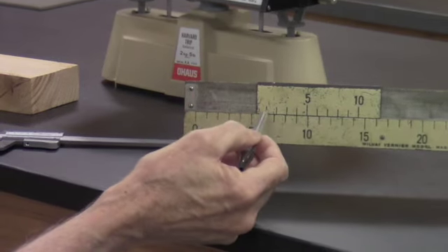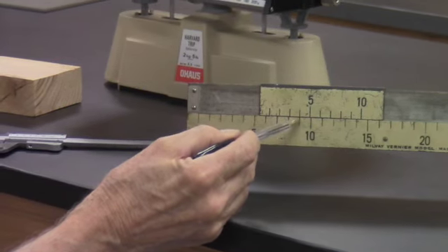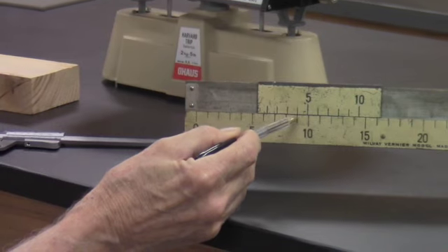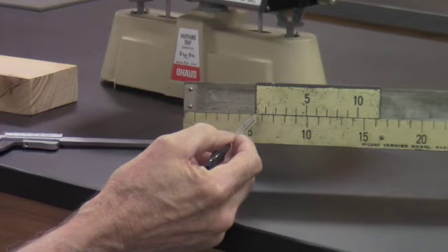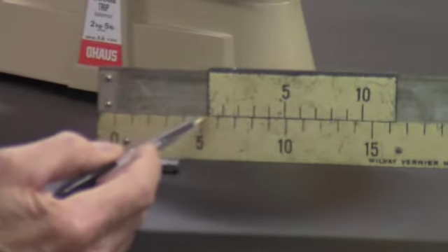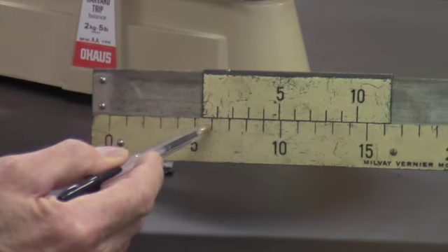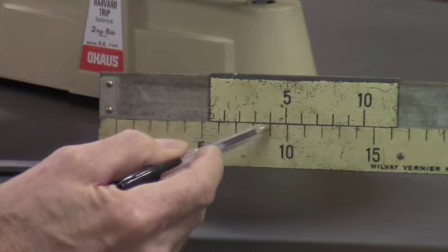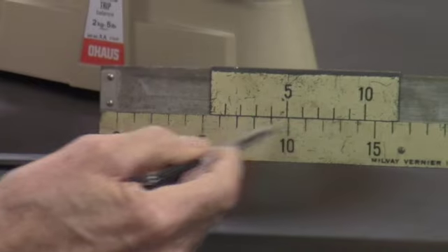And so if you look over here, this line and this line are lined up best above and below each other. And so what that means is this is 5 point, not 5. You probably look at this a little more carefully and see it's a little bit below 5. It's a little bit below half between this number, 5 and 6. And so it's pretty clear that these two lines line up best with each other out of all the lines on the scale.